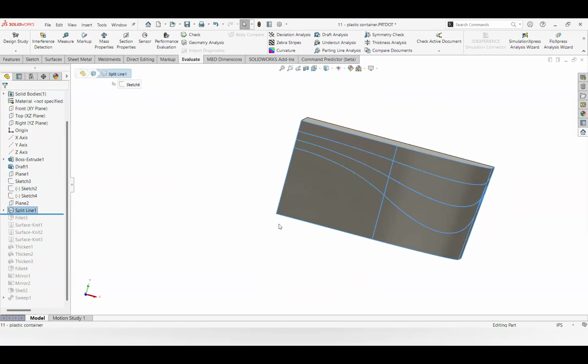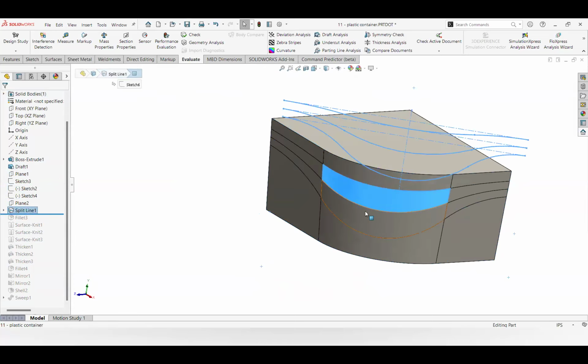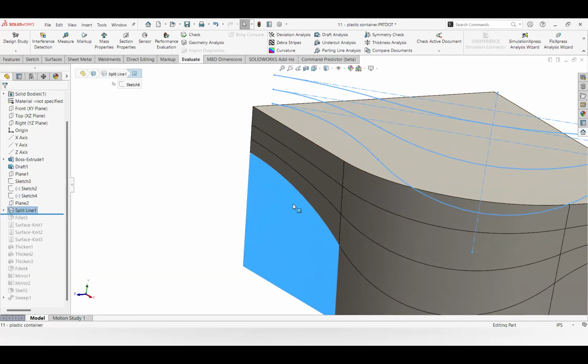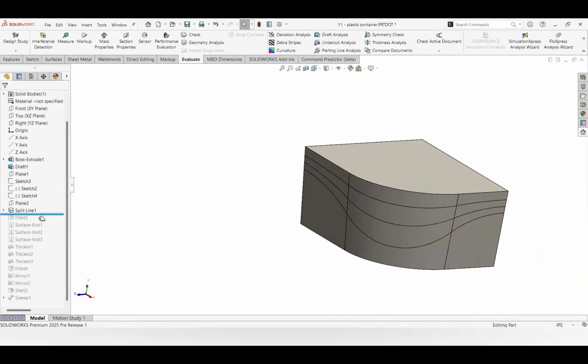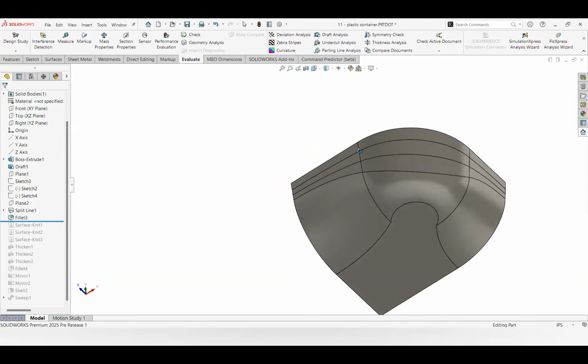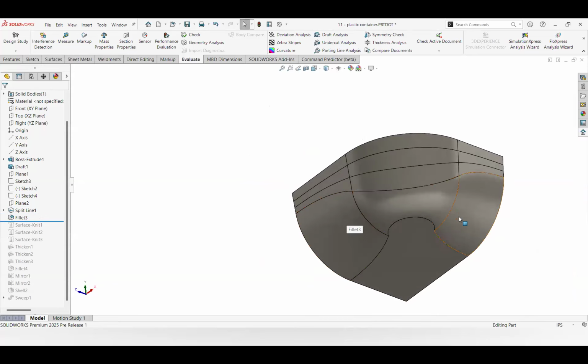So you've probably used a split line before. You can take an existing surface and split it up. Those are all still the same planar face, they just have more edges on them. And has anyone ever used a hold line fillet? This is a fillet that you can apply around this thing, but using this edge as the tangent boundary. So instead of putting in a dimensional value, you're putting in an edge or a curve as the driver of the fillet.